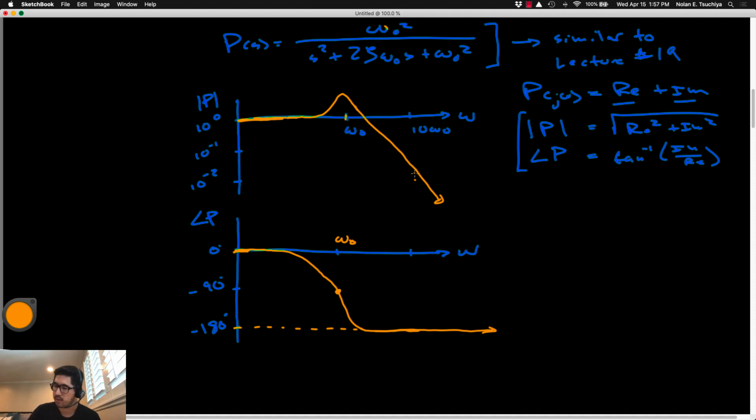Okay. The other thing is that in the Bode magnitude, you're going to see a steeper rate of decay. So for every 1 decade in frequency, you're going to attenuate by 2 decades on the magnitude spectrum. So the slope is steeper for second order, and it's no coincidence that first order is a slope of -1, second order is slope of -2. That carries for higher orders as well.